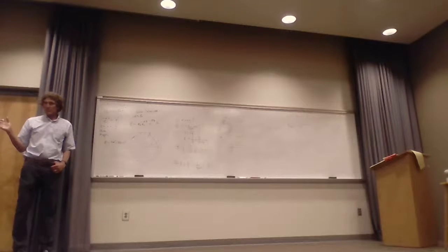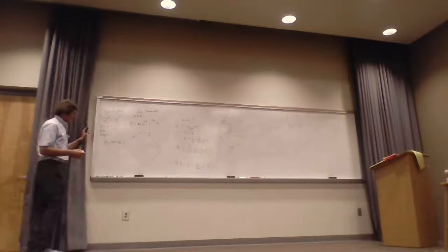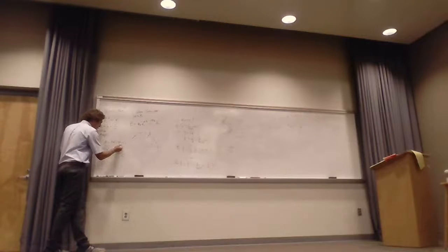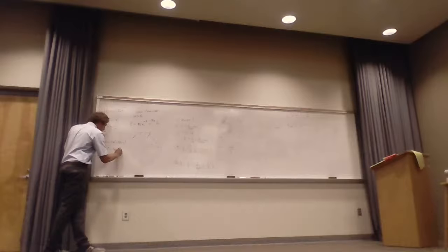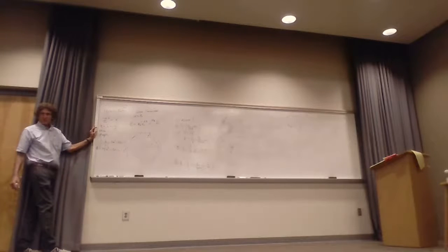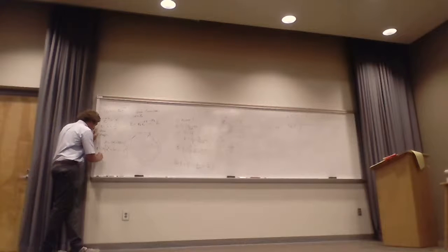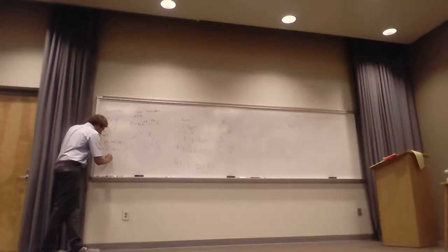All right, I'm going to just show you an approximation that's used all the time. When I do this, what do I really get? I find that the reduced area would be pi out front, times A squared minus, and then it's going to be A squared minus 2A skin depth plus skin depth squared. You all agree with that? I just expanded that A minus skin depth squared. Here I can see the A squared terms cancel, and I'm left with an area of pi times 2A skin depth plus skin depth squared.